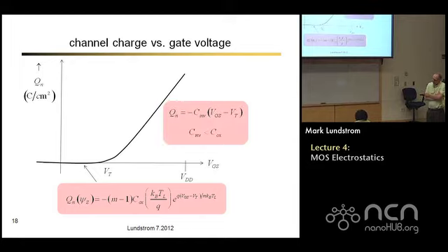Okay, so the point of this lecture, and as I said, we're covering a lot of ground here in one lecture just so that you can generally appreciate what MOS electrostatics is all about. If you take the course with me, we'll have about 3 lectures where we go over this and we can get comfortable with it. But the main points are that it is relatively straightforward to determine what the charge is below threshold. It goes exponentially with gate voltage. It may be small, but it increases exponentially. And that's an expression that people have been using for a long, long time.